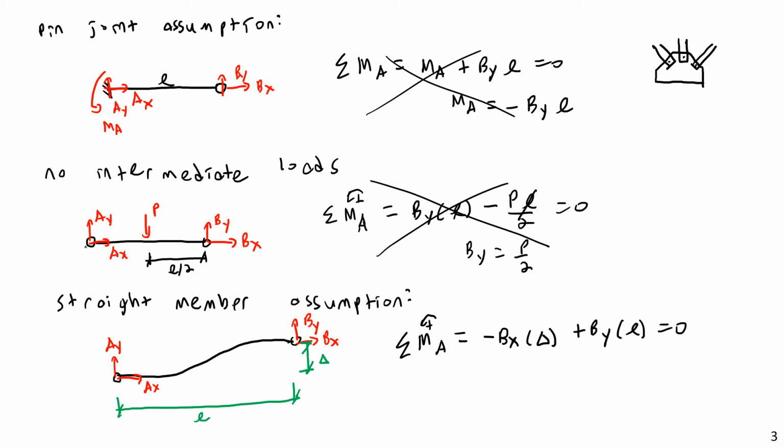Gravity or weight is generated all the way along a member. So regardless of what you do at the joints, you're going to have some load generated in the middle just from the member's own self-weight, if nothing else. But compared to the overall loads of the structure, the weight can be quite small, maybe 5-10% or something like that. In that case, you can treat all of the load as coming into the joints.